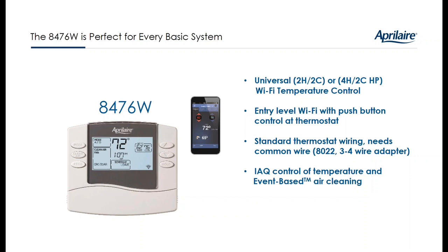We don't offer battery-powered Wi-Fi thermostats. Our concern is that in some applications, the Wi-Fi information, due to interference or signal strength issues, may need to be repeated quite a bit, and that might drain the batteries sooner than a year. We want to make sure that if we're going to use batteries, they last at least a year, so all of our Wi-Fi thermostats are 24-volt powered right from the HVAC system.